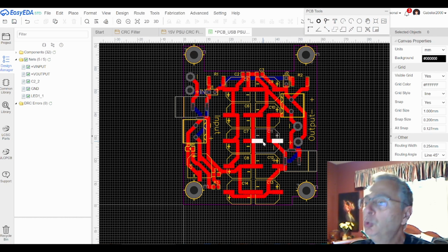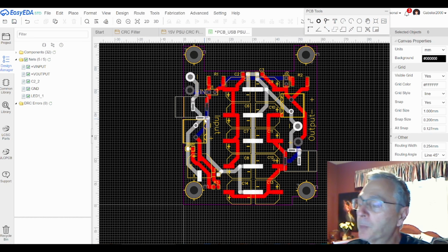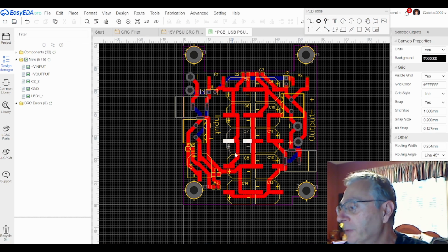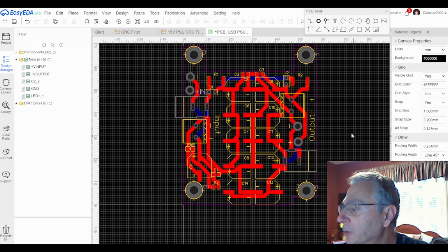The last thing you want to do is your copper pour. You see how it's all just traces, but there is no copper holding all of the ground and all that stuff. So we're going to start on this part here, and instead of all, we're going to click on copper. We're going to see where the pencil is, basically where things are happening.